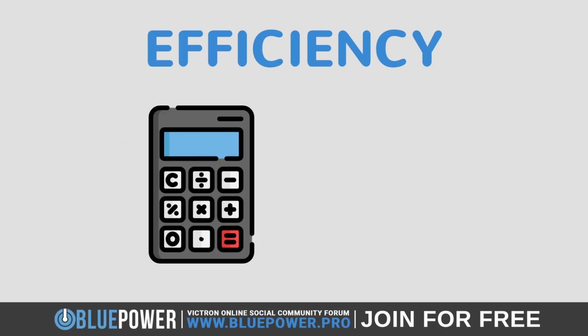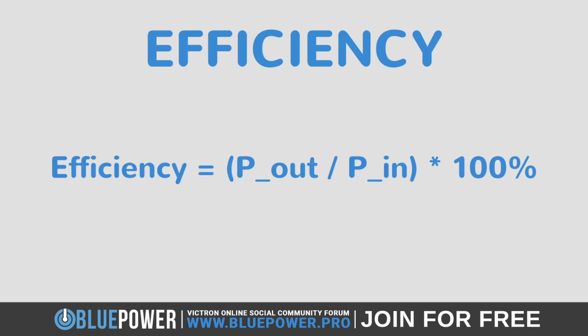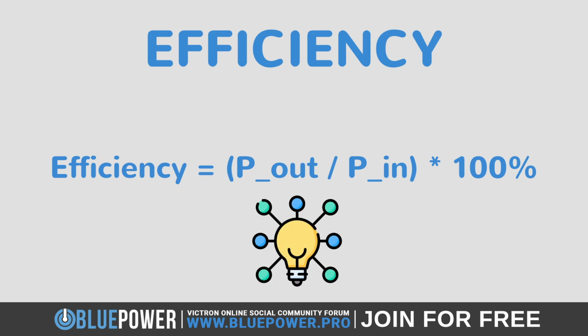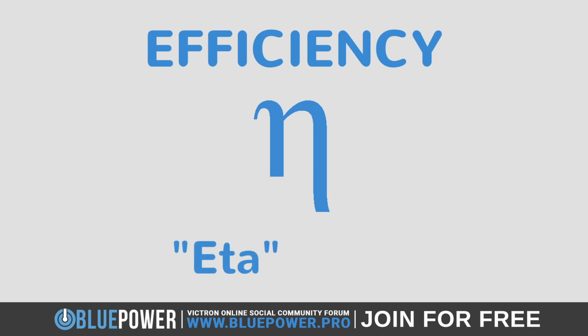So, in order to calculate efficiency, we naturally need a formula, which in its most basic form looks like this. Here we can see that efficiency is equal to the output power divided by the input power multiplied by 100 in order to get a percentage value. While I will be explaining a much more in-depth version of this formula later in this video, this basic version will help you to better understand the concept for the time being. Note that the efficiency is denoted by a Greek letter that looks like a lowercase n. However, it's actually pronounced eta or eta, depending on who you speak to.